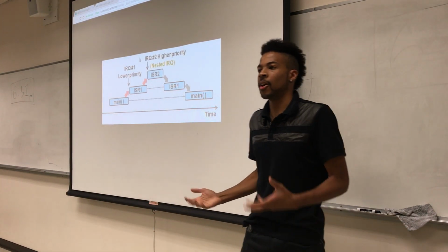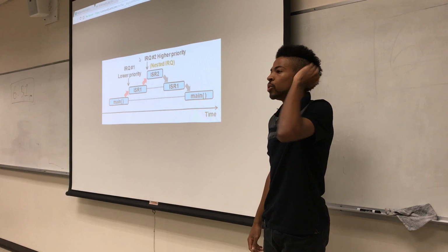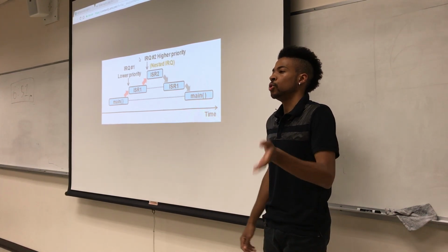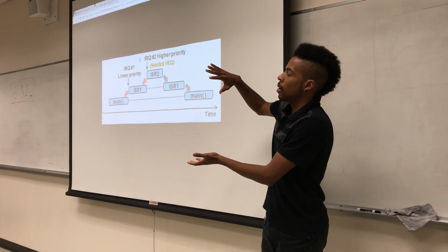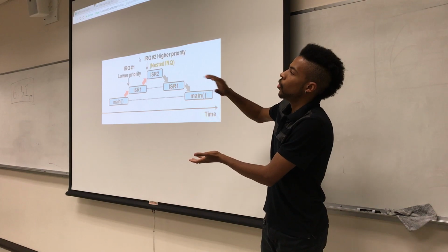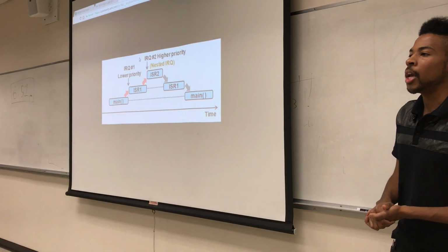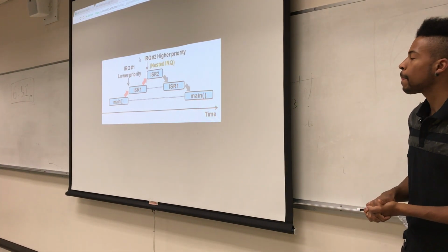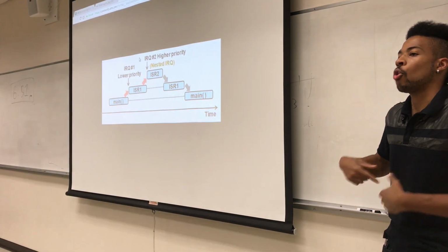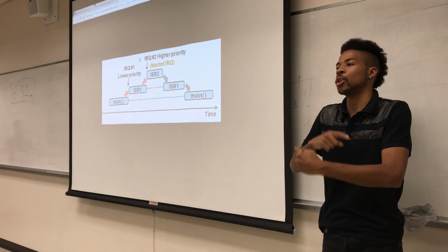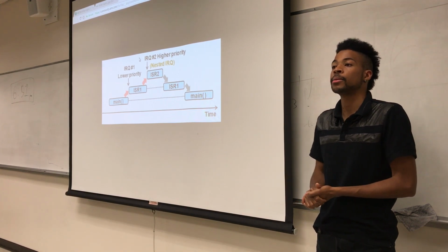Similar to FreeRTOS. FreeRTOS is very similar to an interrupt system. And actually, back in the day, a lot of people just used interrupt priority systems, NVIC systems, to do the different tasks. You could set up a timer and have different tasks that you could run within that. You can give each task its own priority level, and you just use the nested interrupt system for that. Fun fact, typically FreeRTOS runs at the lowest priority level, such that if there are any other hardware interrupts, they will jump over to that rather than having FreeRTOS run over them. Because there's not really a chance for FreeRTOS to stop running to allow the other lower priority tasks to run.